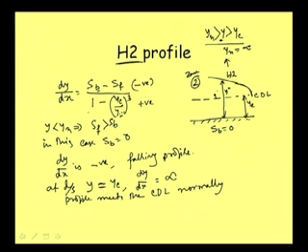And at the upstream side, if we keep on going, in real situation, as we said, this horizontal portion will be a small portion. There may be a situation that a mild slope is coming like this, then some portion is horizontal, then again the channel is going. In nature also we can have this sort of situation. Now, if it is like that, then this will indicate what will happen at the upstream end. And without considering that, just mathematically if we think that we have a very long horizontal portion, then at upstream y may become very large, and the difference between yn and y may reduce, and we can have some analysis on that part.